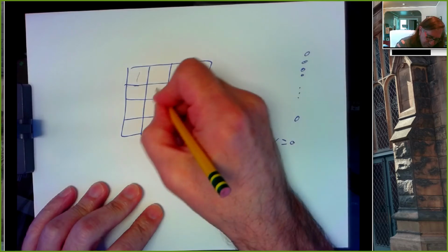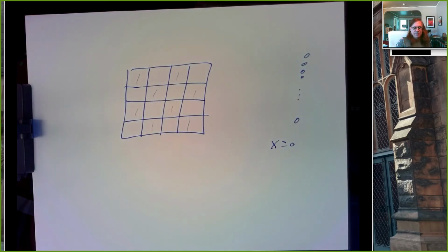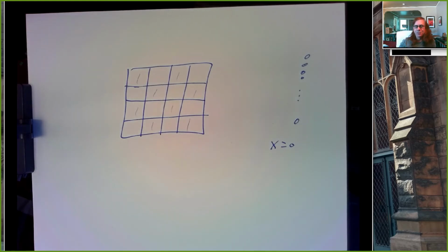Here's a really unpleasant K-map. So how would I cover this with rectangles? You'd have to do 1x1s for each of them? Yep. Only thing you can do here is 8 1x1s, and each of those is going to be a 4-input AND gate, and you're going to have to OR those together. This is one of the 2 worst possible truth tables to try to simplify with a K-map, because all you can do is 1x1 squares.